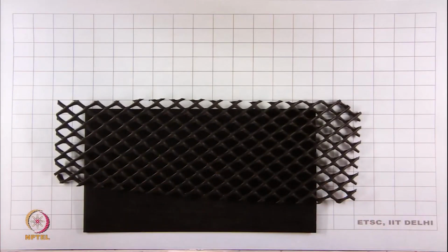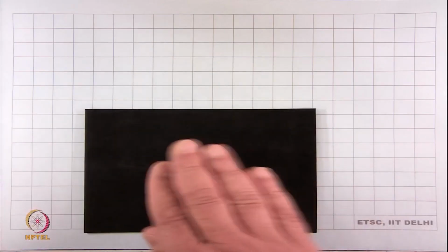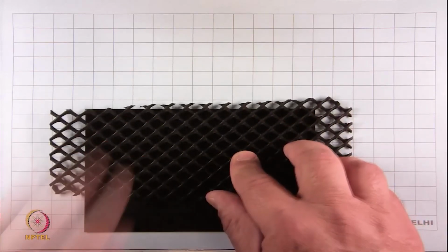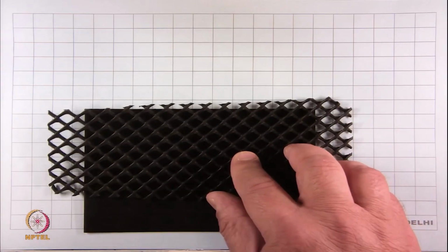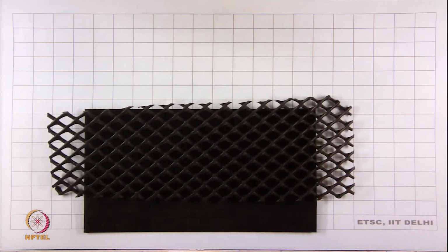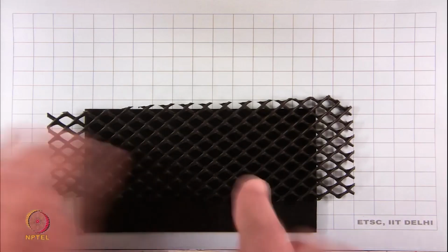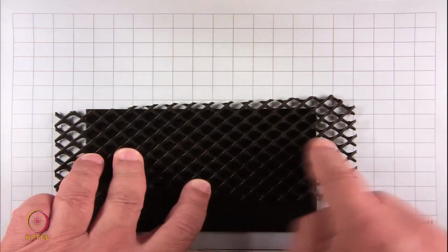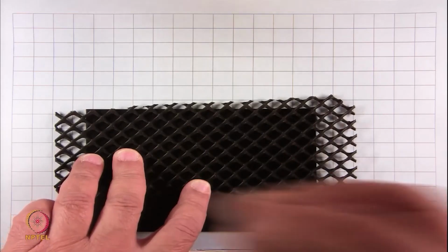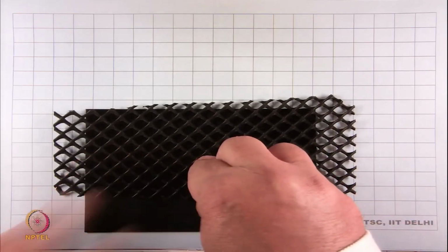Can this net replace the sand? That's the question. The water will be percolating down from the surface layer and the protective layer into the drainage layer. It will come and rest on the geomembrane. If I have a net on top, which means there is a finite thickness of air space on top, and if this is sloping downwards, then water can flow along the plane like that. I am bothered about the fact that fines should not come into this. So what will I do to prevent fines?